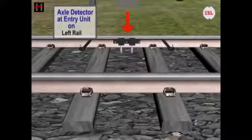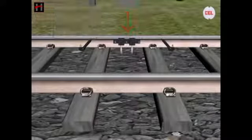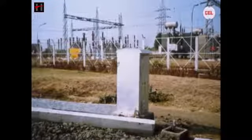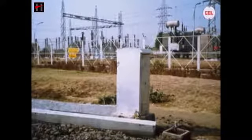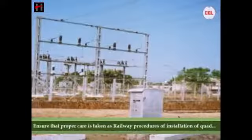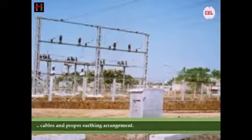The axle detectors should not be installed with entry unit on the left rail and exit unit on the right rail of the track at entry and exit of the section. This will result in both units being counted as in count or out count. While selecting the site for axle detectors near high voltage SSPs and feeder stations, ensure that proper care is taken as per railway procedures of installation of quad cables and proper earthing arrangement.